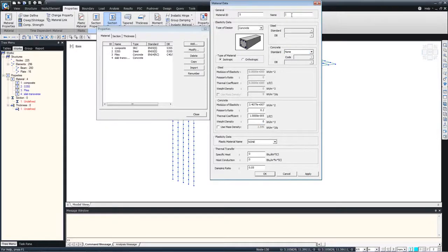Then say, for example, I want to have a material for the longitudinal concrete parts, so that I can consider the time dependent effects like creep and shrinkage, which we will also see later on, how we can consider them along with the composite action. So I'll create a material for the slab.